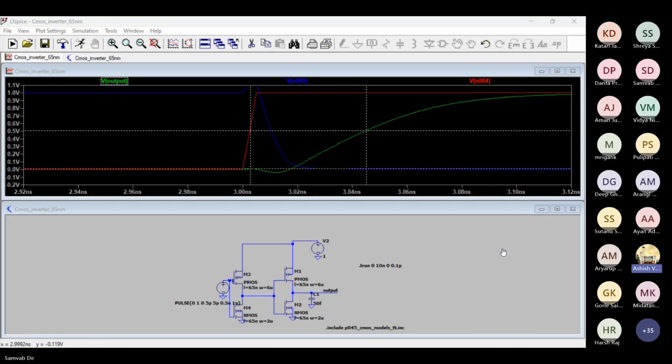Sir, the capacitor appearing at the gate-source of the circuit. Yes, gate to source capacitor for the NMOS and the PMOS, and also the drain-source capacitance of the first stage NMOS. In the MOSFET model, have you read any drain to source capacitor?